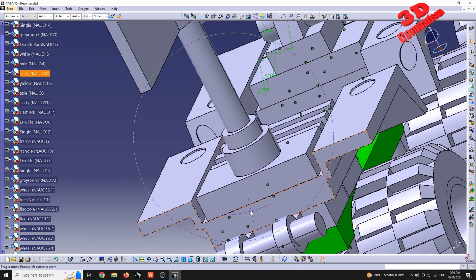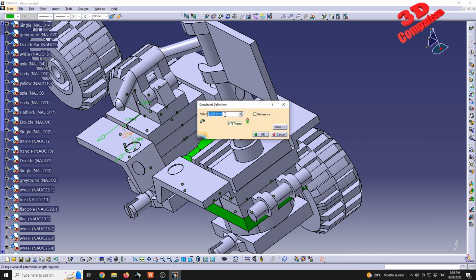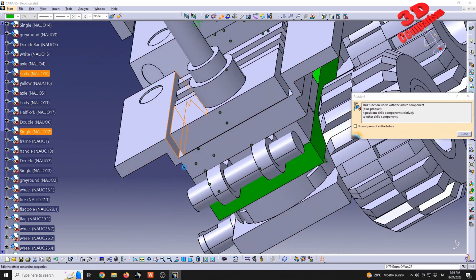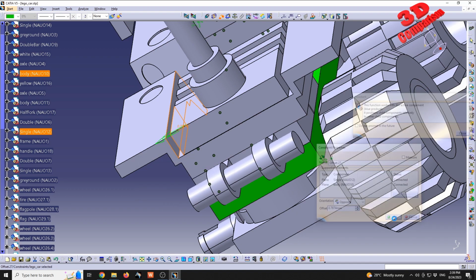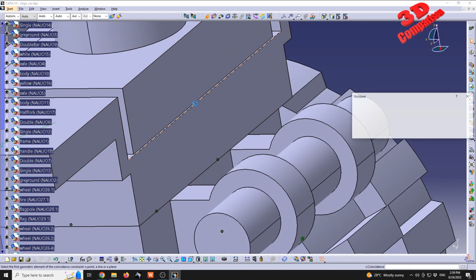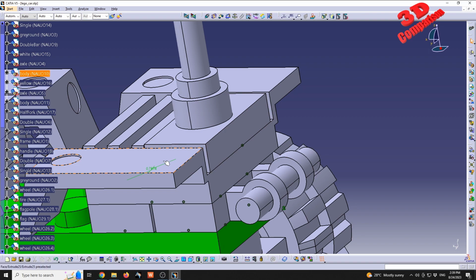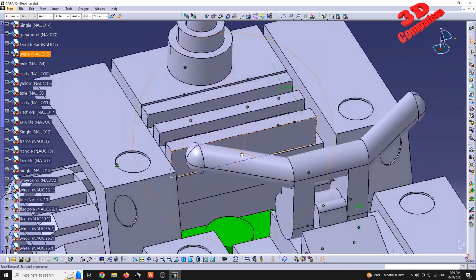So we see that those components are not properly aligned, and we know the value because it's the same value as here. I'm gonna double click, press Ctrl+C to copy, and we are gonna maintain the same offset between the inner part and the interior of this one. And I just pasted the value, and we see that the part slightly adjusted. Now I'm also gonna put edge to edge over here. So that piece should be fully locked because we have this offset distance and we have that edge. But now we still need to address this part over here.